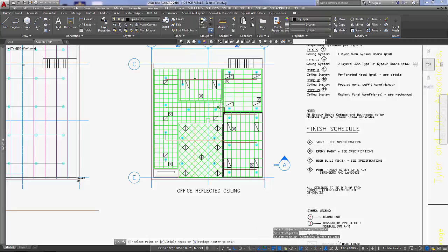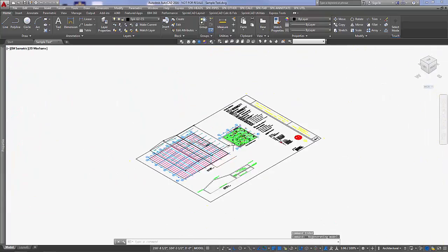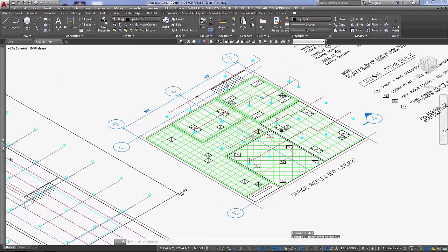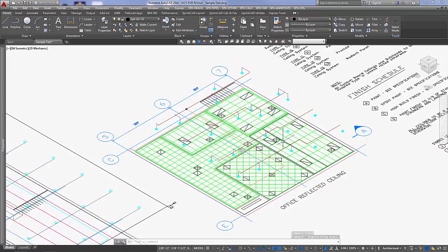And even when the branch line is broken crossing the main, as they are here, the heads can be selected all along the run, and they'll be connected without creating overlapping pipes. And this command isn't just for connecting sprinkler heads to branches, it can be used to route piping between any 2 points. I will leave the 4 heads in the bottom right hand corner to demonstrate flex drops. Here you can see the goosenecks in single line view.